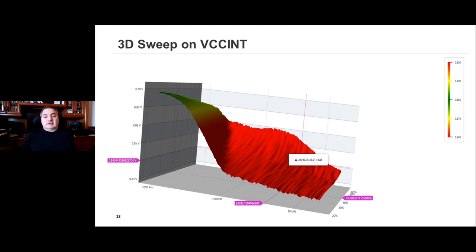So there's two major tests that we perform to spot weaknesses in a power supply or a PDN quickly, whether it be the controller or the caps or whatever it is down the PDN. And the first one is where you sweep, as Rob did in that very brief demo. We sweep duty cycle.